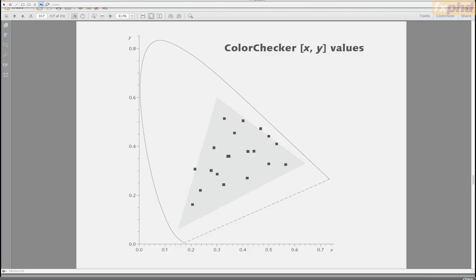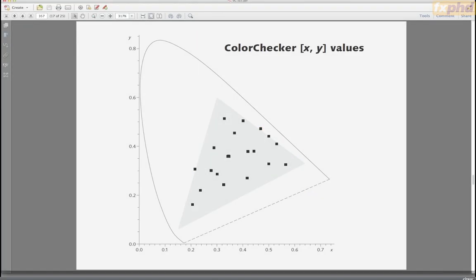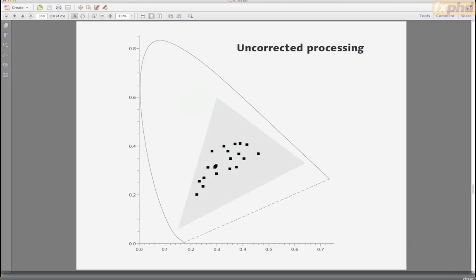So now, second step, let's take the camera, point it at the Macbeth chart, and then just directly take the RGBs, hook them up to a 709 display, and see what colors we get. These are the colors you get. So basically, if you don't do any electronic processing in a matrix, you find the colors look really undersaturated. They look like pastels, and the picture looks wrong.